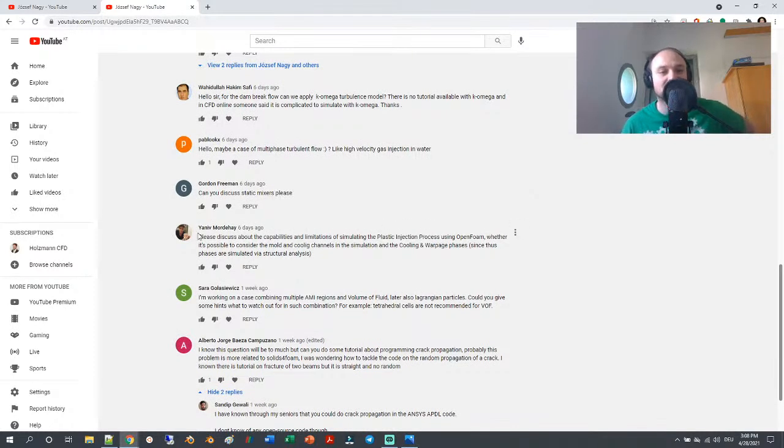Please discuss, Yaniv, the capabilities and limitations of simulating the plastic injection process using OpenFOAM, whether it's possible to consider the mold and cooling channels in a simulation, and cooling and warpage phases, since those phases are simulated via structural analysis. I could talk about this for an hour because I did this as a postdoc before I started Eulerian Solutions. So theoretically, yes, but not out of the box.